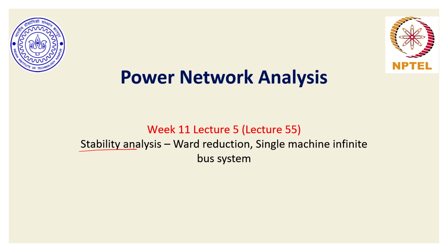And in this discussion, we'll take up a method of reducing power network buses into buses which only represent internal EMFs of the synchronous generators for transient rotor angle stability analysis, because synchronous machines have to be represented by the internal EMFs in series with direct axis transient reactance Xd dash.